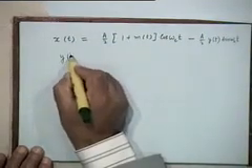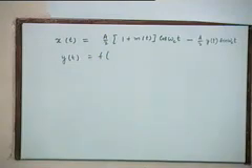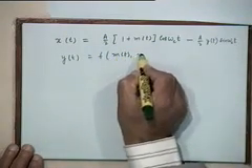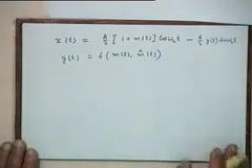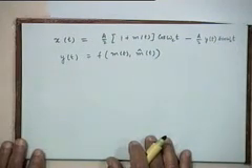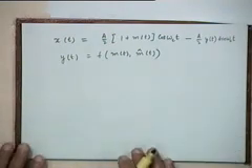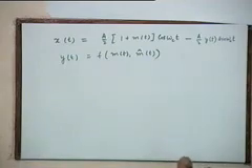where y(t) will be, we will see soon, a function of both the message signal and its Hilbert transform. It will not be just the Hilbert transform of m(t), right? So we can have this kind of representation, and if this kind of representation is possible, we can do perfect synchronous demodulation or approximate envelope demodulation, right?